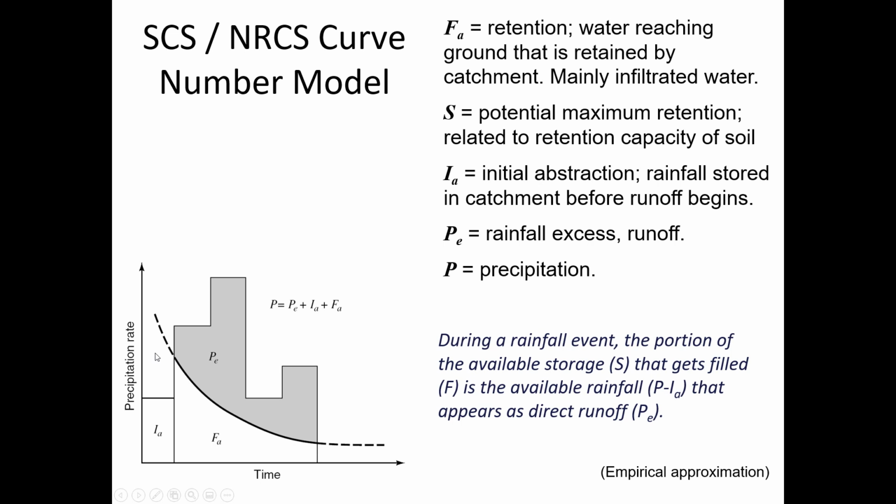So to the left of this curve, all of the water has been absorbed. And it's only when you're to the right of this point of intersection that there's leftover water beyond what the ground is able to infiltrate. So that's why this dashed line was the potential infiltration. It wasn't yet an actual infiltration rate because it could have absorbed more water than it did. But there was only this much rainfall.